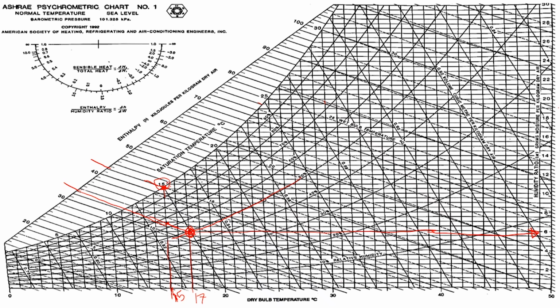So we can see here the process is dropping down but on this specific line. So this is the specific volume line. So this process is a constant volume process, which is known as isometric, and since it is going down, it is isometric dehumidification.